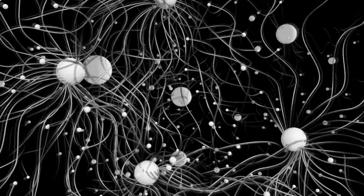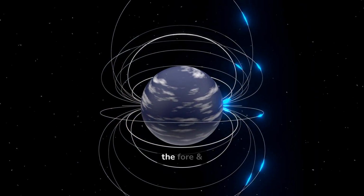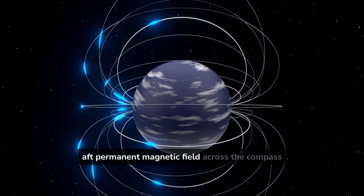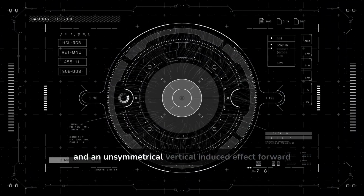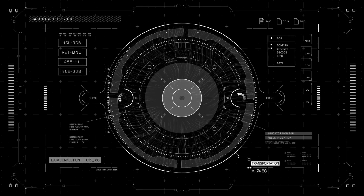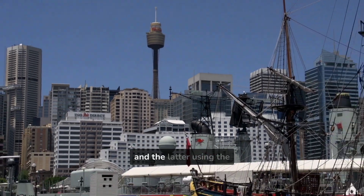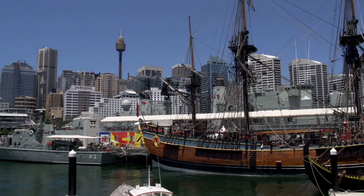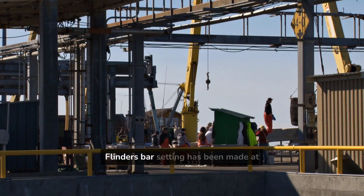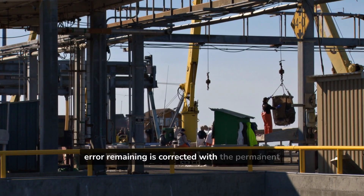The B error results from two different causes: the fore and aft permanent magnetic field across the compass and an unsymmetrical vertical induced effect forward or aft of the compass. The former is corrected using fore and aft magnets, B, and the latter using the Flinders bar. Inasmuch as the Flinders bar setting has been made at dockside, any B error remaining is corrected with the permanent magnets, fore and aft.